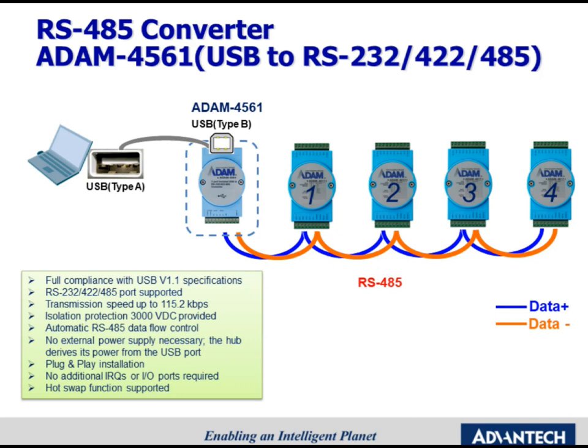Another converter is the USB to RS485 converter. Since USB is also a common interface, this module is more special and convenient because the USB port can provide the power for the ADAM module, so you don't need to connect a power supply for this converter.